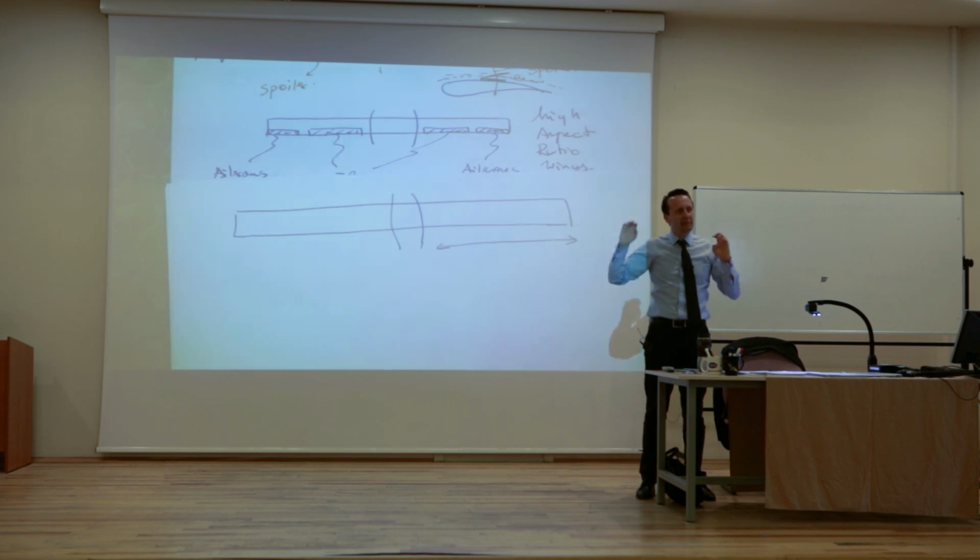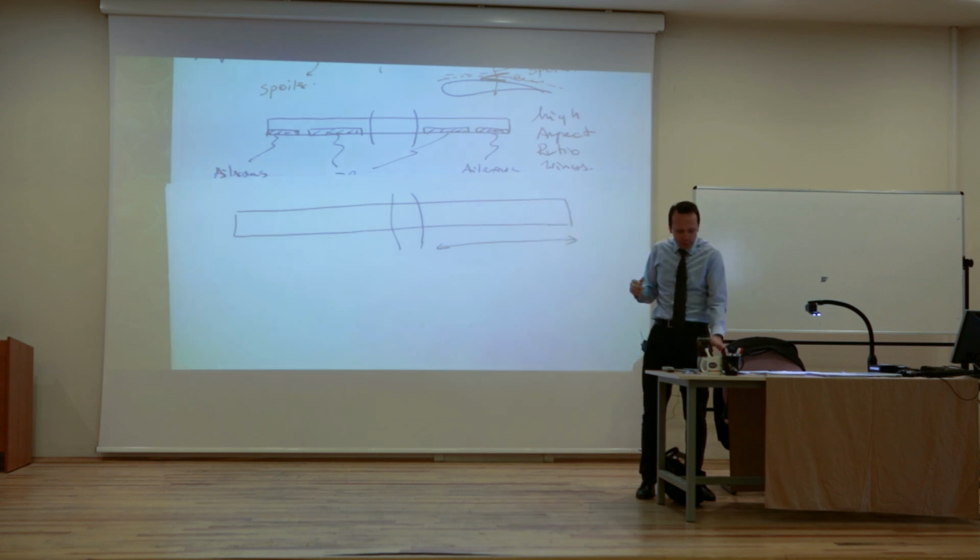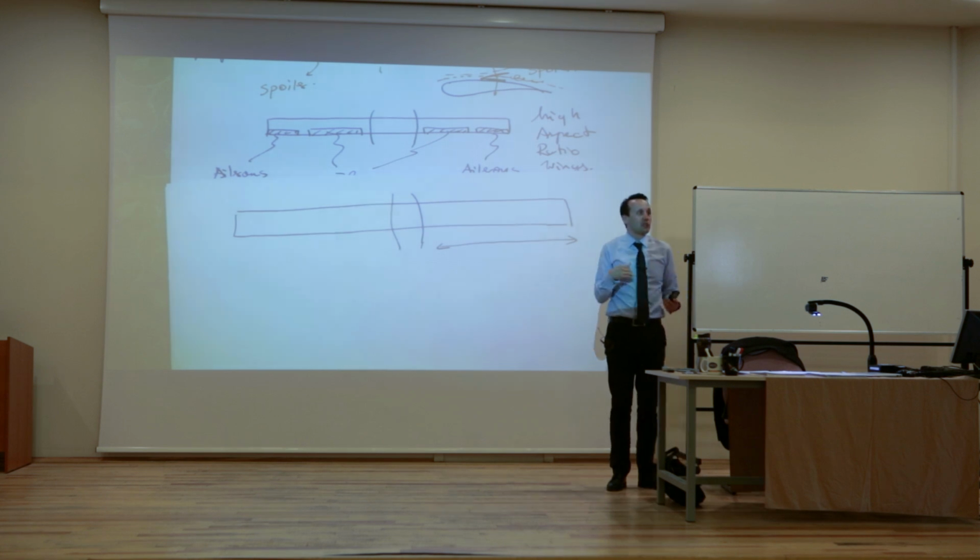You can cancel oscillation with another vibratory input. So the aileron can actually move a little bit like that and cancel that oscillation. So you could use the aileron for structural control, in order to avoid those vibrations.